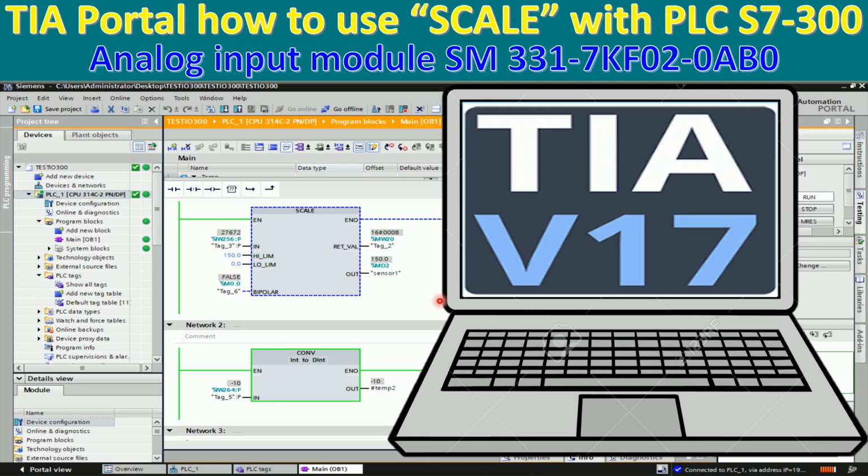Today I would like to show and share about TIA Portal version 17, how to use the scale and unscale with the PLC S7-300 for input, analog input and output module. Okay. And here is the scale block that we can use to convert the analog input signal to the actual value of the electrical devices, or we can scale another value that we want. Okay,